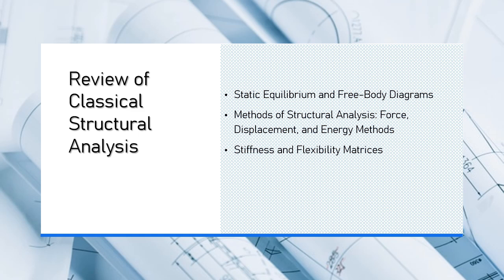In statically indeterminate structures, there are more unknowns than available equilibrium equations. The force method starts by choosing one or more of these unknowns, called redundants, and removing them to make the system statically determinate. Solving the determinate system: once the redundant forces are removed, the structure becomes statically determinate, and we can solve for the reactions and internal forces using equilibrium equations. Applying compatibility conditions.